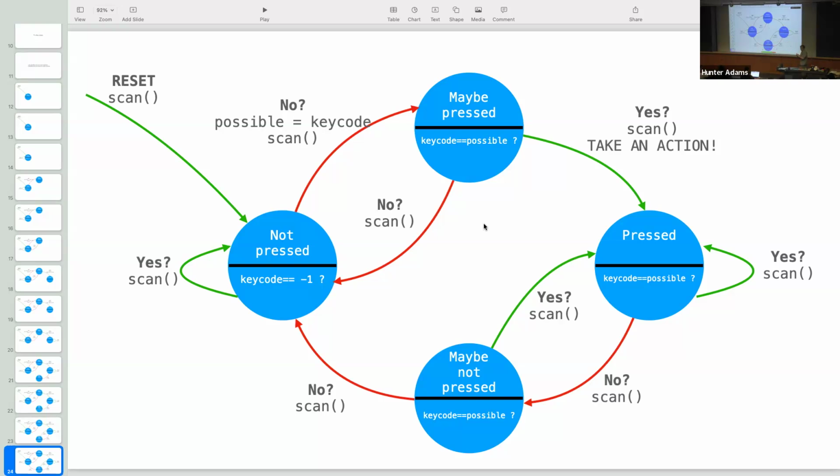There's one more piece of clarity to add here, which is the lab 1 specification is that you get 1 sound per button press. So let's say you have the chirp on button 2, so that when the user pushes button 2, a chirp comes out. The user should be able to push button 2 and hear 1 chirp, and if they push and hold button 2, it's still just 1 chirp. To get a second chirp, they have to lift their finger and push it again.